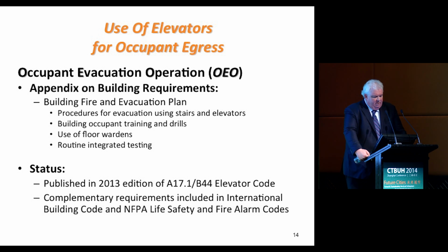The other thing that's critical to this is there must be a building fire and evacuation plan, and that plan needs to include procedures for evacuation using both stairs and elevators. It needs to include building occupant training and drills. It should consider the use of floor wardens to direct people, and also there should be routine testing of the entire system.